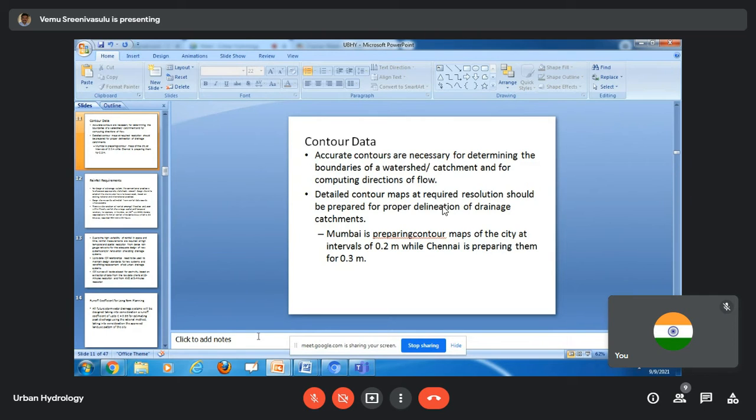Thematic layer means it represents one theme. Similarly, if you have rainfall data at different locations, then we can apply the Thiessen polygon method using spatial data and calculate the average rainfall over the study area. So like that, there is a lot of data you have to build before running the model.